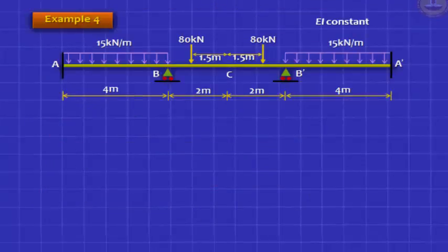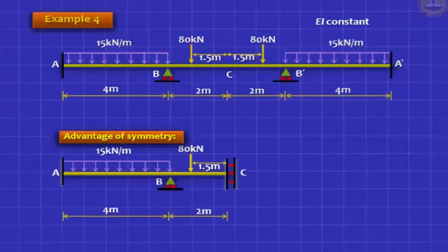Let's take this problem, okay? It's the same problem as we did earlier, except that there's no support at C. How do you do this problem? Very interesting. Give it a shot. First, take advantage of symmetry, which means you cut the beam at the axis of symmetry and put guided fixed supports there.